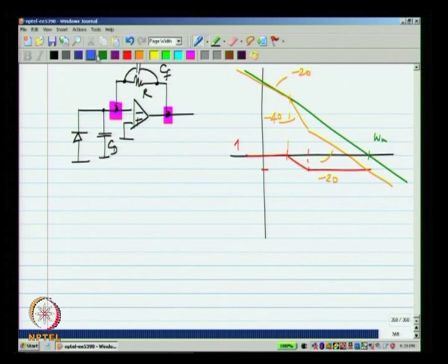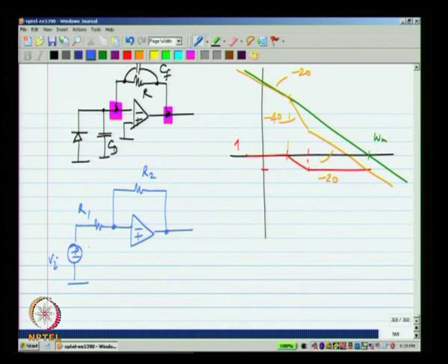Okay. Now, just a last quick remark, this technique is also useful when we have an inverting amplifier. Okay. Now, there will always be some parasitic capacitance here. If you reduce this combination to a Norton equivalent, we will have a current source at the input, and that looks exactly the same as that one, okay, except for a shunt resistance R1. So, in this case also, by putting a capacitor across R2, you can do some things.